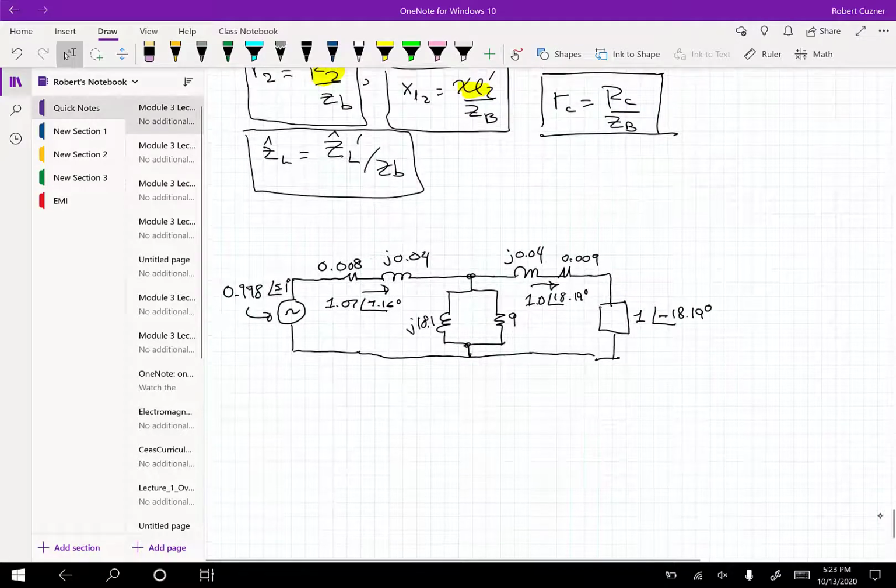It tells me if I were going to design this transformer to supply 1.0 per unit current or 100% current to a load, if I define the rating on the load side of the transformer, at least here for this leading power factor scenario, I would have to derate the transformer. I'd have to actually design the transformer to handle more than 100% load continuously, probably 10% at least,